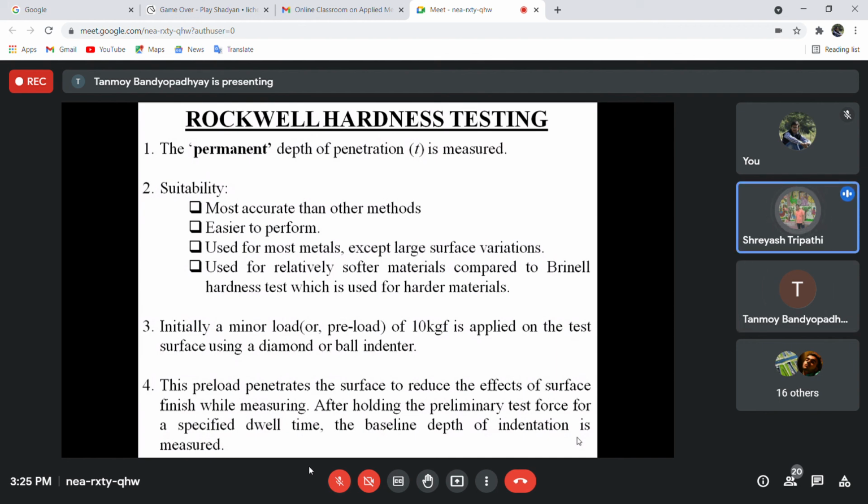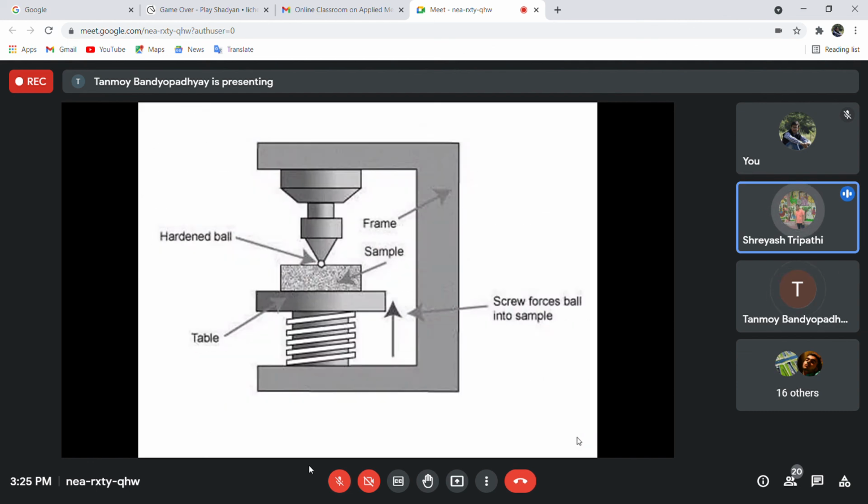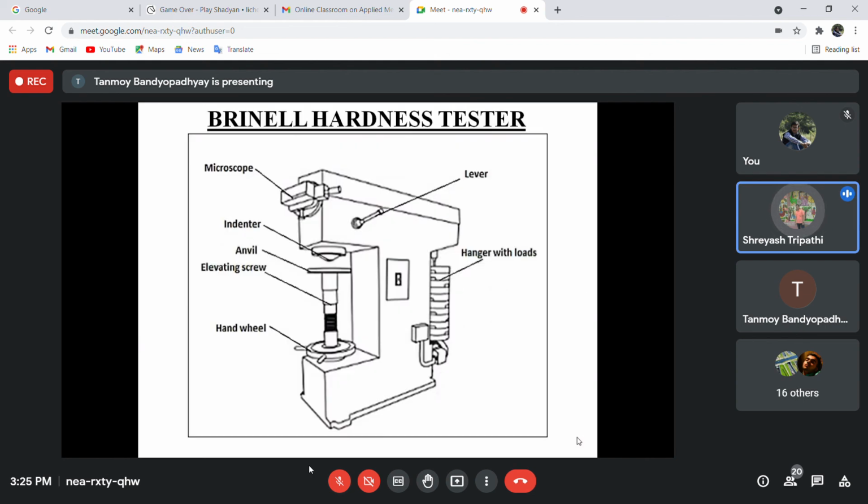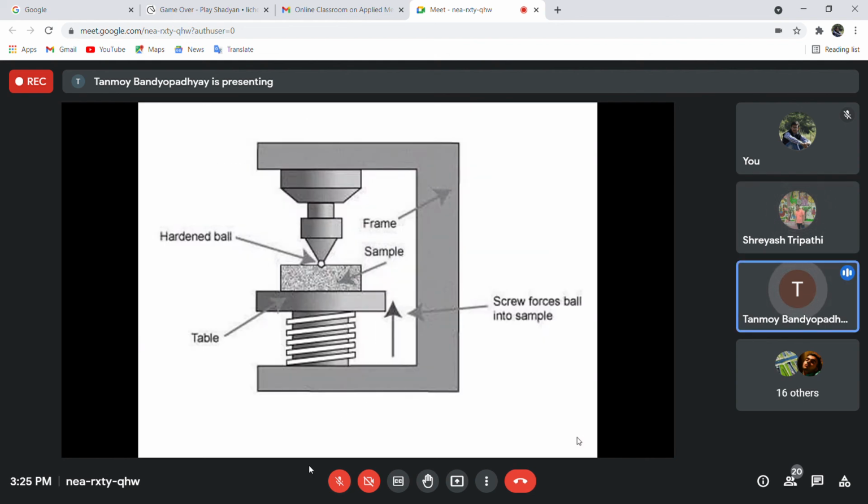Actually, I have a doubt, sir. If the indenter and the body have the same value of force, and we are applying the same force, then there will be no deformation. No deformation, but generally we choose an indenter that has a higher hardness. Always we choose the indenter, suppose steel, diamond, carbide. So all those things that have higher hardness act as indenters. Whenever you are testing, you cannot test a carbide specimen using a steel indenter. So for a carbide specimen, you have to take something that has a higher value of hardness, say diamond and all.